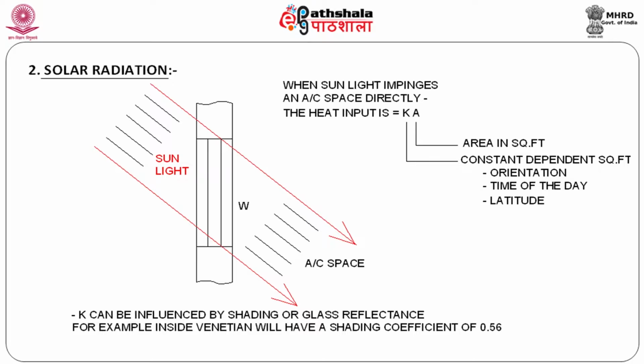The second item that we had looked at was solar heat gain. Solar heat gain is incumbent only as long as sun comes into the AC space. Obviously, if you want to restrict this, a very simple thing is to shade the window, which means sun does not come in. Now, I am quite sure if you look at any fundamental book on air conditioning, a good author will start on by saying shade is the cheapest form of air conditioning. What he meant was that when you shade a space, you take care of things like radiation, etc. automatically.